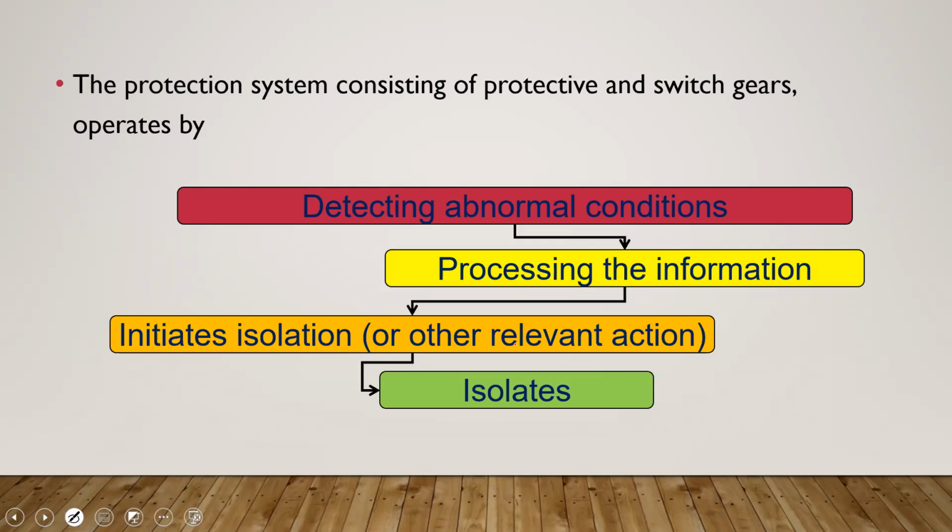Which means that if the lizard can get in there and have a beautiful life, then moisture can get in. So you can have that breaker's spring mechanism for tripping becoming corroded over time. So when you have a fault, for whatever reason, it simply will not trip.